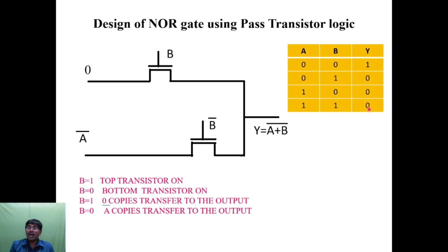So now we have to assign the data input as 0. Then only, whatever the input will be, when you are assigning B is equal to high input, this 0 will be transferred to the output. So that is why the table says so. Now when both are 0, what about the control input? A bar. When both are 1, the data input is 0, the output will be 0. Data input 1, the output will be 0. That is, irrelevant of the input, the output will be the same.